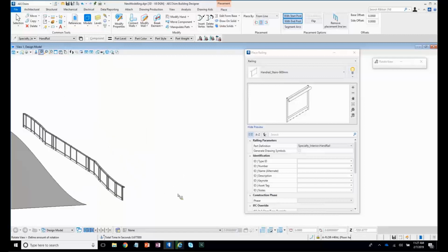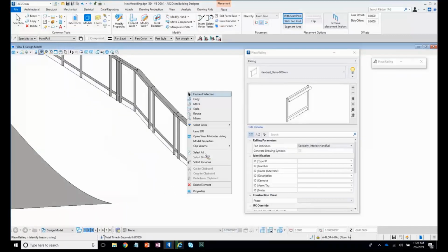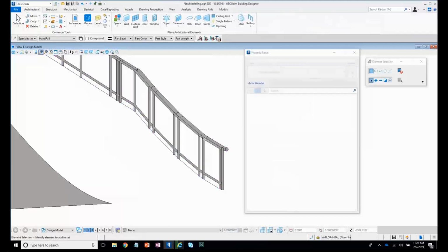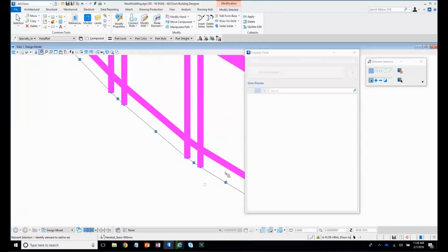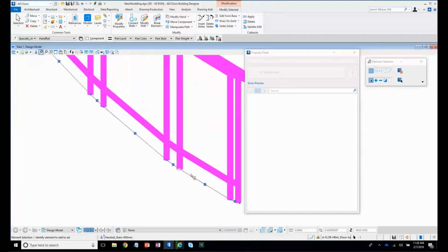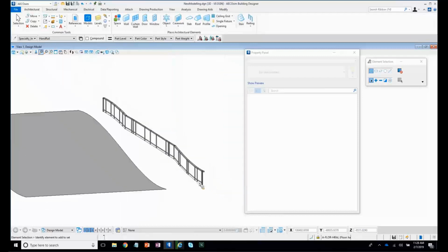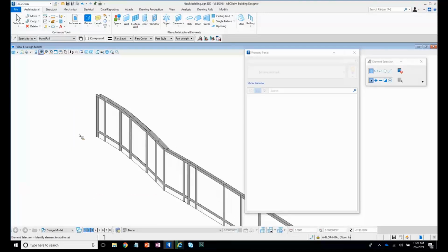Okay. Now we could click on this now, it's railing, and you'll see the ribbon bar change to reflect we may want to have some other tools to work with. So let's say I wanted to move this post down a bit, wasn't quite happy with its position. I can do that, and it will shift the post down to where I need it to be. Okay. So we're not fixed in with working with just the building tools in the one environment. We can actually mix and match the type of tools we'd like to work with here.